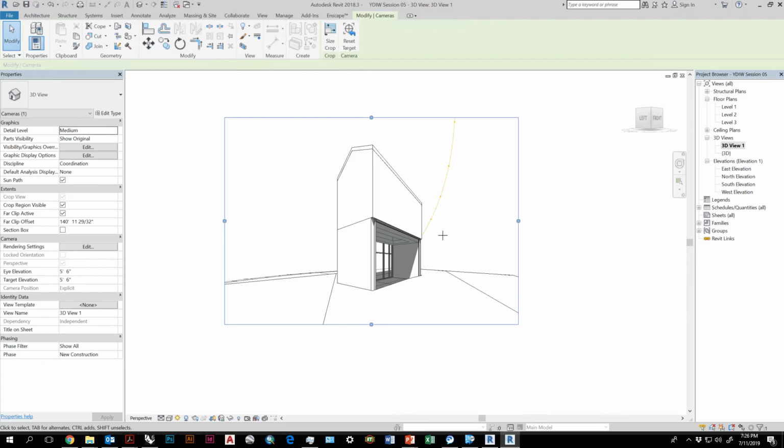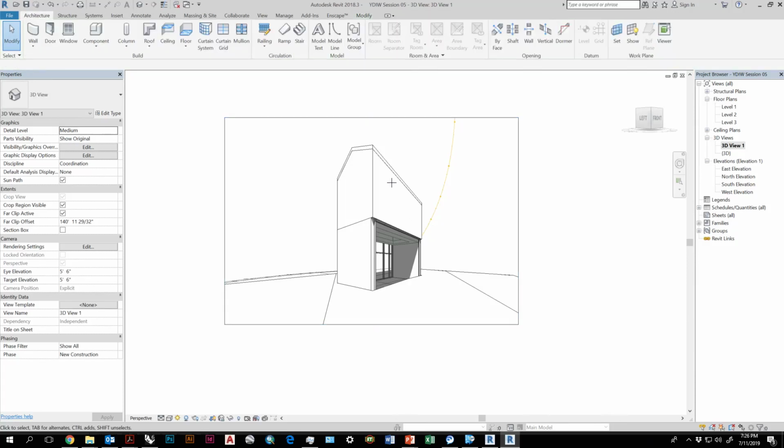Okay, so let's say you wanted to export a building's line work and a building's shadow for drawing. You can't do them both at the same time. If you export a drawing with shadows on, shadows are a raster element. It will rasterize everything and you won't be able to edit anything. So this is how I found that you can do both. If you're making an Illustrator drawing straight out of Revit, this is how you do it.